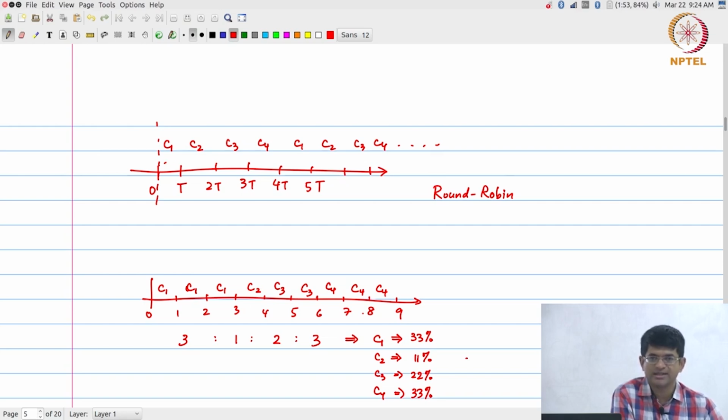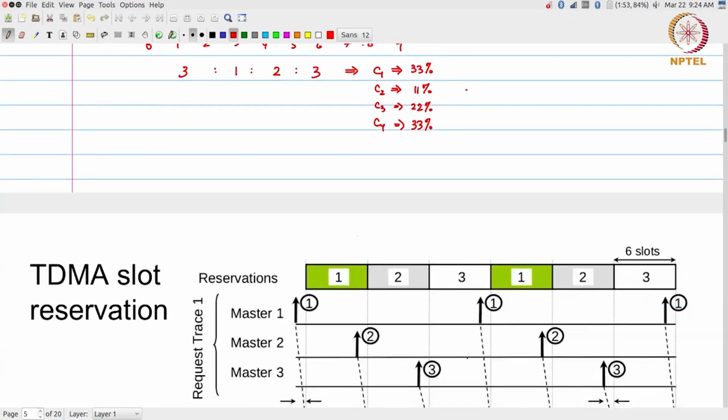Because all that it says is everyone is guaranteed to get their amount of bandwidth, right? It's decided ahead of time. So as far as the bus implementation is concerned, it becomes very simple, right? The bus doesn't even need to actually look for request signals. It just has one small counter and switches assignment after so many cycles, okay? Of course, it has a problem.